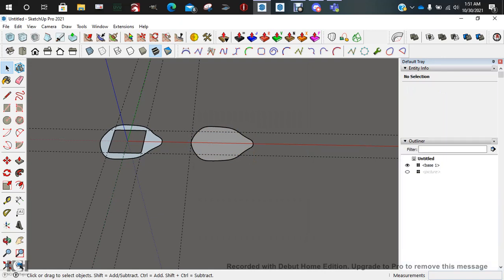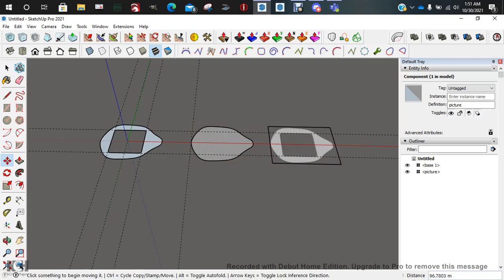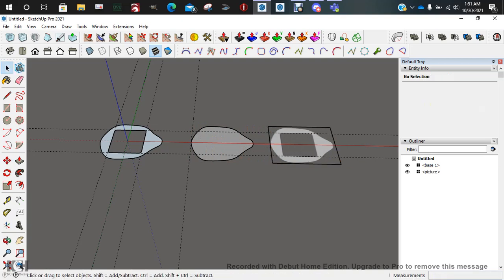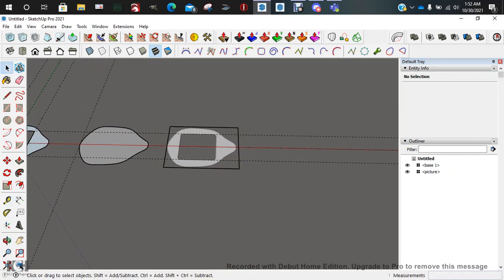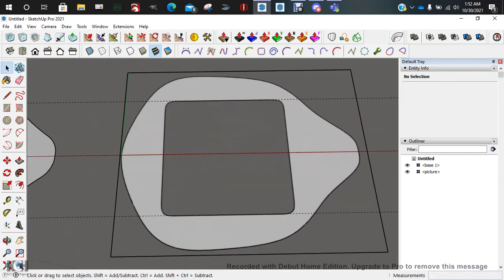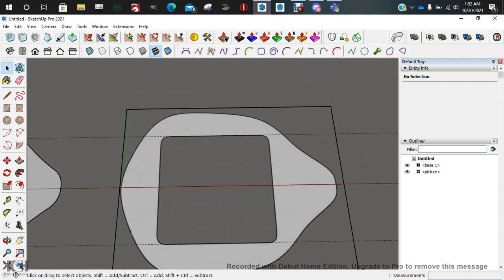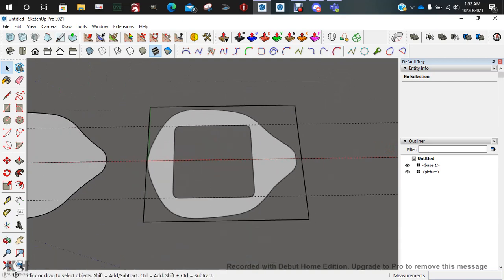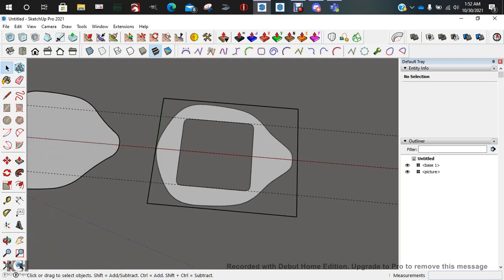Now I'm going to unhide my picture, and we're going to move the picture down so we can try another technique. Hit T for tape measure. We're going to get our guide back, and this time we're going to use one of the spline tools and compare it. Now notice I used 48 sides for this, so I want to use something similar or higher. The 3 best, I'll just kind of run through them.